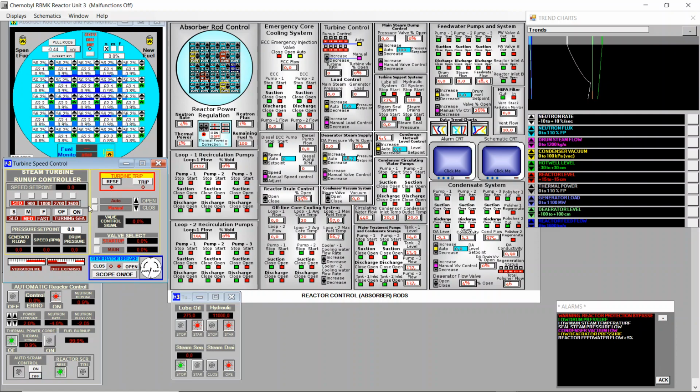When this LED lights up, we switch on the turning gear, and we see the speed set point increasing now when it reaches 20 RPMs, which is the turning gear. It's an electric motor that spins the turbine mechanically to be ready to start taking steam. Okay, it's at 20, so now we can start the steam seal, and at this point the turbine could already be turned with steam from the primary system.